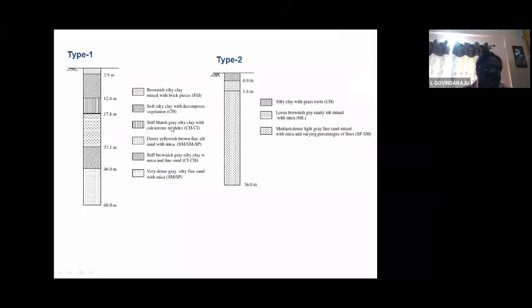It is only clay. Here it is silty, soft clay. And then this is bluish gray silty clay, dense yellow fine silt, and then stiff brownish silt, and very dense fine sand. Only sand and silt mixtures existing for a great depth. As I mentioned earlier, the depth of overburden plays a dominant role on the ground response studies, and definitely the damage potential is exponential.